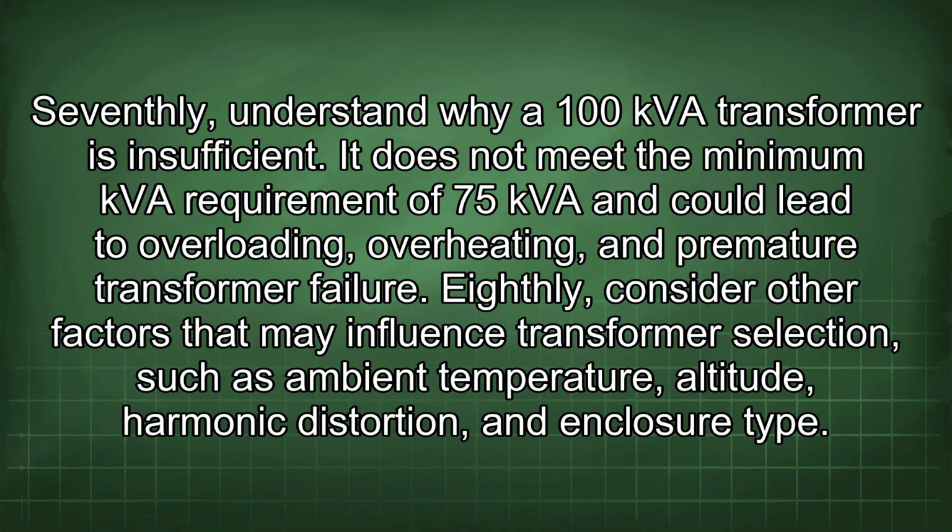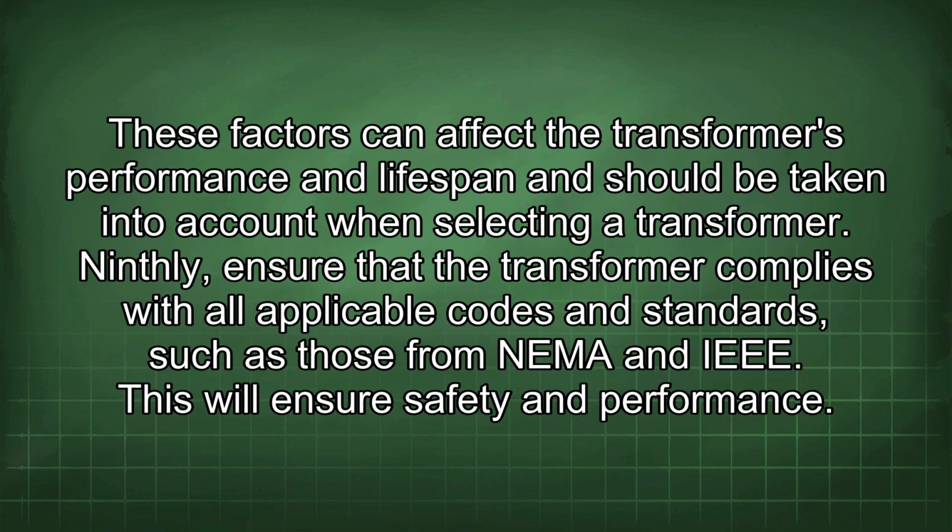It does not meet the minimum kVA requirement of 75 kVA and could lead to overloading, overheating, and premature transformer failure. Eighthly, consider other factors that may influence transformer selection, such as ambient temperature, altitude, harmonic distortion, and enclosure type. These factors can affect the transformer's performance and lifespan and should be taken into account when selecting a transformer.